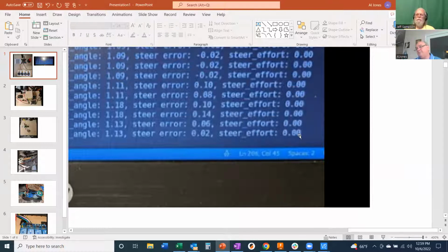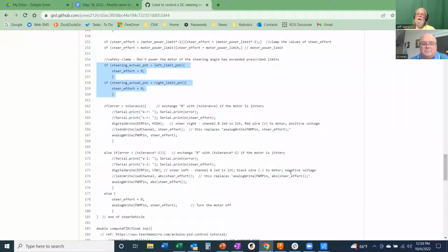Okay. And back to your point, yes, you can use the analog write. That'll work. That's proven, and everybody knows that works. So at this point you're probably better off just using that, even though it's noisy. And then once you get everything working right, you can switch over to a different driver function to do that.